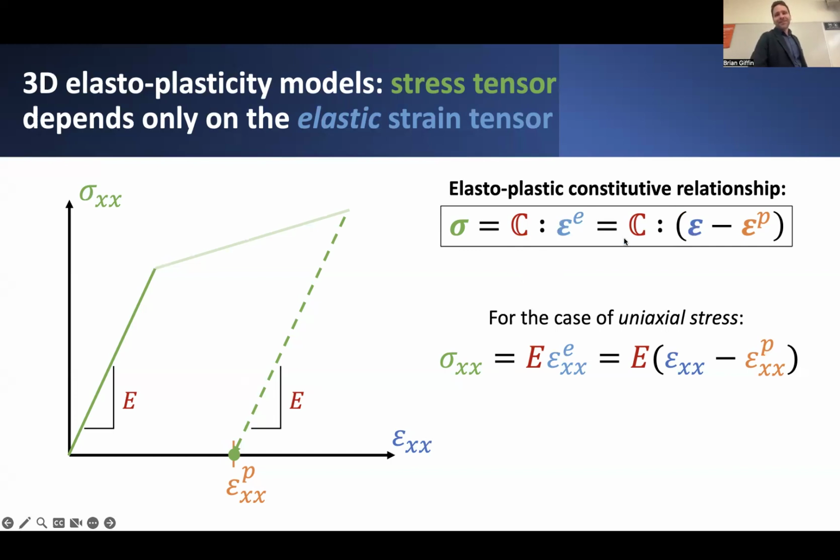So if you assume that the other components of strain are potentially non-zero, but you suppose that the other components of stress apart from sigma xx are equal to 0, then you actually get something that depends directly on just the elastic modulus. So that's kind of nice. We get agreement with the uniaxial, simple one-dimensional idealization that we developed previously.